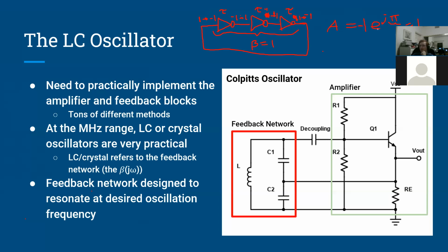Yeah, exactly. Got it. And so this type of oscillator is used all over digital CMOS circuits or integrated circuits. You don't see it that much for communication circuits or wireless systems, and the reason is that it has what's called a low quality factor, and that increases the phase noise of the oscillation, which again is like the jitter in the frequency.